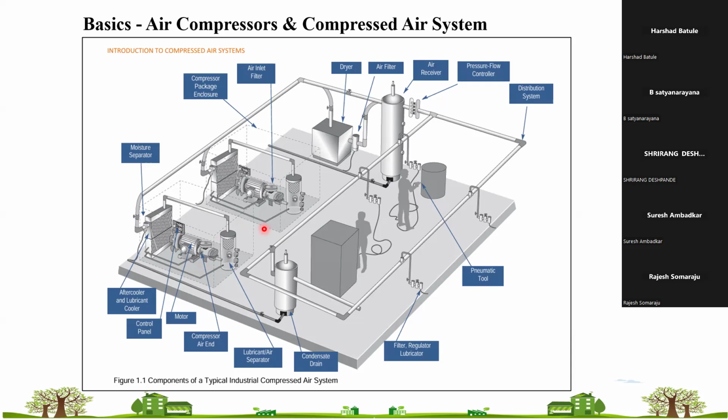The formula for leakages in the system is load cycle time divided by load cycle time plus unload cycle time, into 100, meaning percentage. So your 10 divided by 10 plus 60, so 10 divided by 70. 1 by 7 is around 13-14. So 13-14 percent there are leakages in your system, because we don't have operations right now.